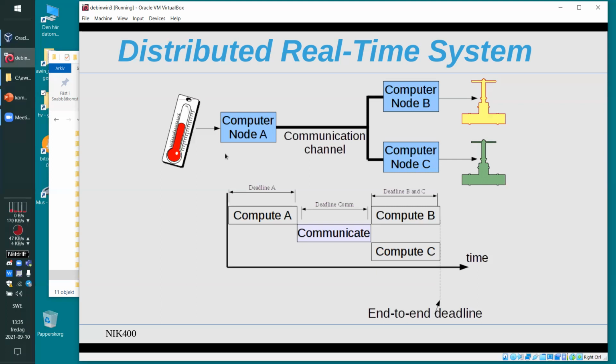That means every, let's see, like 5 milliseconds, you send a new packet here. If the packet is received here at exactly the same time each cycle, you have a jitter of 0. It's perfectly deterministic in some way. And jitter of 0 means that it's exactly the same receive time each time.